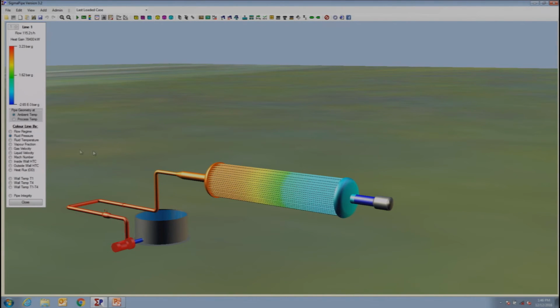If you look at temperatures, what you find is an interesting thing. The temperatures are picking up as you go through here, but you reach a peak at the outlet of the heat exchanger and then it drops down again. Now, why on earth would it do that? The answer is partly to do with gas velocity. If you look at what the gas velocities are doing, you see that all that steam in this DN 450 line is running at 330-something meters a second. It is ripping through there really fast. Is that close to sonic or supersonic? Well, if we look at the Mach number, no, 0.67, it's still subsonic, but it's running pretty darn quickly.